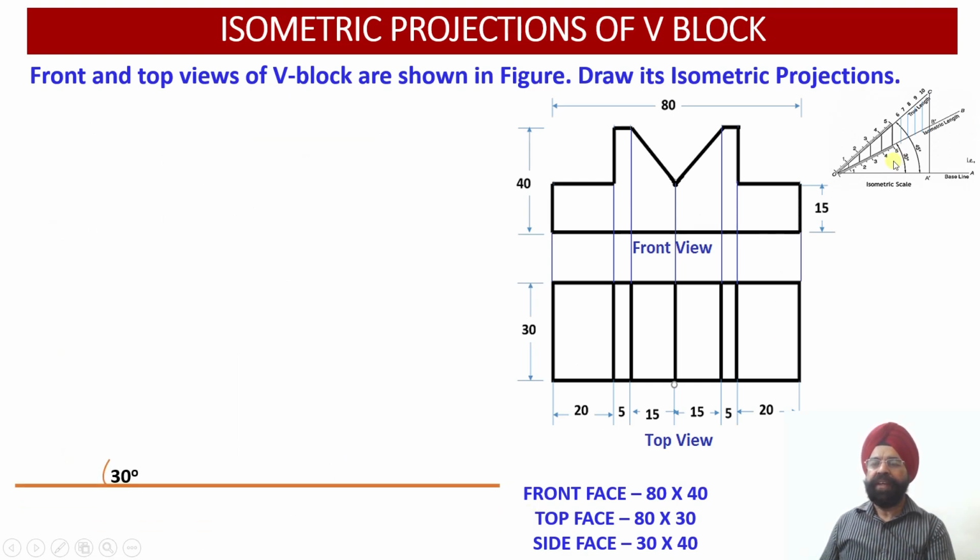So step 1, we have the isometric length scale drawn, and then conversion of all the dimensions into the isometric lengths. Then we have the ground line. So please check, this is our horizontal ground line or the datum line. Now on this line, the x-axis will be drawn along the left side. So please check, we have drawn the side view towards the x-axis side. Okay, so this is the x-axis side, and in the side view there are two things which will be available.